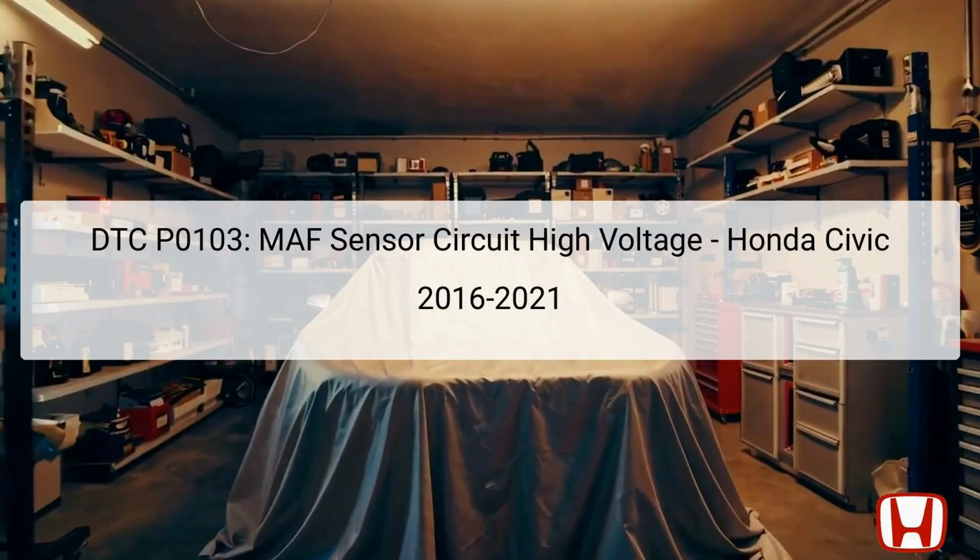The Diagnostic Trouble Code, DTC P0103, indicates an issue specifically related to the mass airflow MAF sensor circuit in Honda Civic models from 2016 to 2021. When this code is triggered, it signifies that the MAF sensor is reporting a high voltage signal, which suggests potential problems within the sensor or the circuit itself.